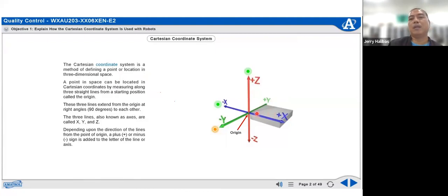Say, you draw along the Y. But take note, it is not in reference to the coordinates you see in the properties of the robot. It's the tool frame in reference with the reference frame or the base. So it is not the TCP coordinates you look at but rather the base. Those XYZ values will be displayed here.